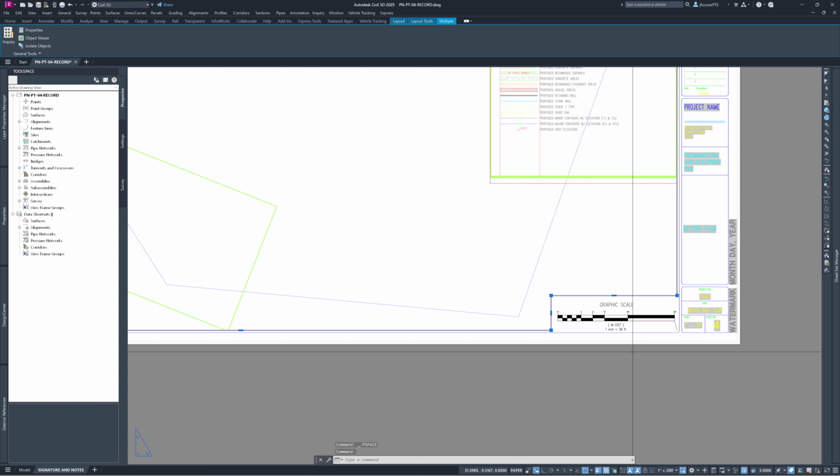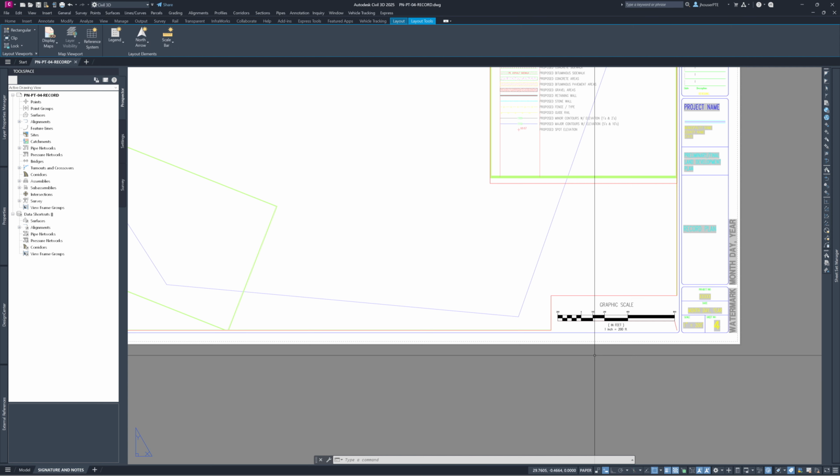I'm going to lock that viewport, and now this graphic scale is not connected to it, so you do have to change it, but you can hit on that little arrow there. And if I regen the whole plan, you'll see that the title block is updated to the main Windows scale. This all only works if you leave the template alone and you do not delete this viewport. If you delete this viewport, this will turn to, I believe, X's or percent signs or something like that. It will look weird. You'll have to go through it and reapply it to the correct viewport.